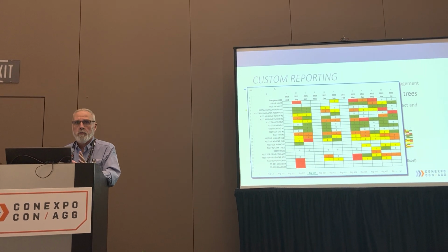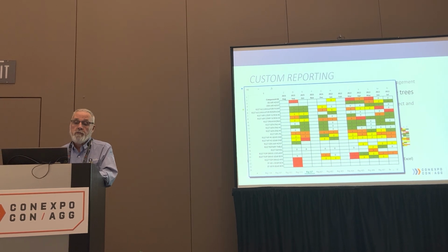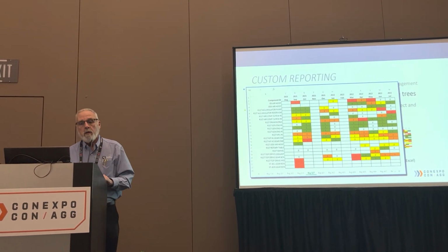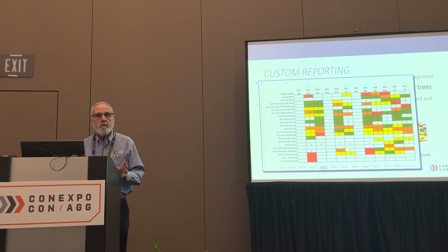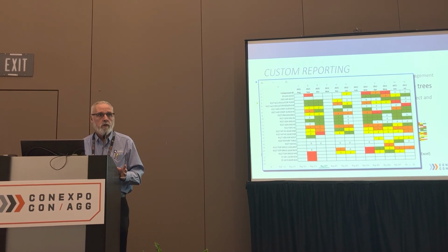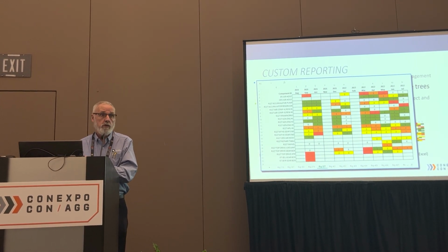That's always a consideration, operational demands, right? Give you a great example. When I was in mining, we said, all right, we can definitely go from a 500 hour drain interval, without doubt, just looking at the data, to 600 hours.